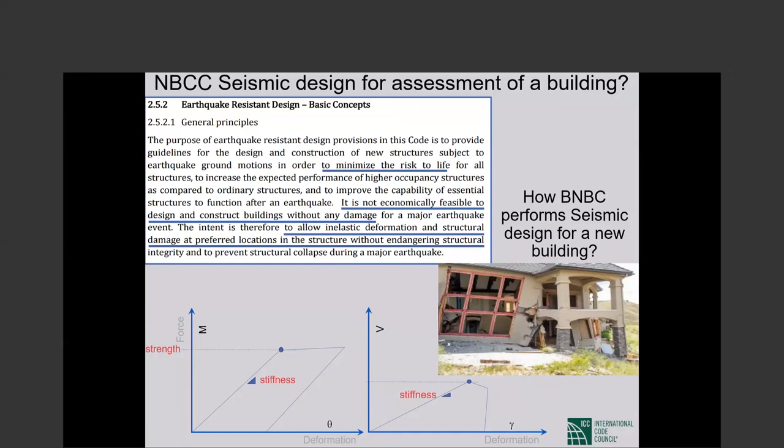No, everything was so simple: calculating a base shear, distributing it along the height, and using an elastic model and software, calculating the response parameters in the elements, and then going to the code and designing so that the strength is more than the demand. So where is this complex behavior that I have shown down there, where do we look at it?